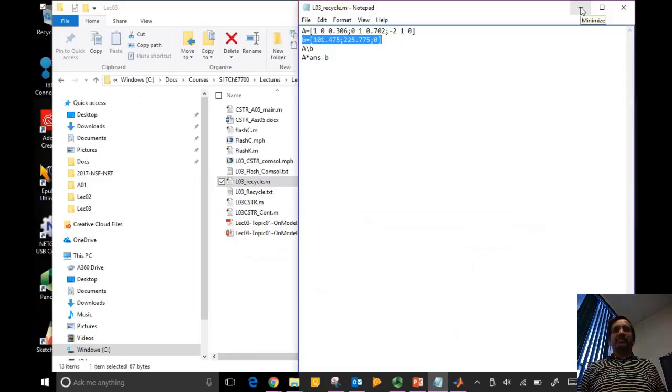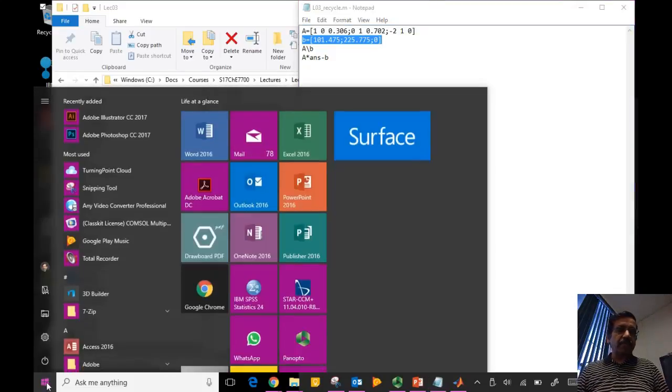It's a bit cumbersome. MATLAB is very elegant for these kinds of problems, but COMSOL is very elegant for solving partial differential equations. For solving algebraic, linear or nonlinear, and ordinary differential equations, initial value problem or boundary value problem, MATLAB is very good, very convenient. When you go to PDEs, MATLAB gets very complicated to use. But COMSOL traverses that trajectory very well. But you cannot write one line like A equals in COMSOL. You need to enter the whole function. So let's just start how that would look.